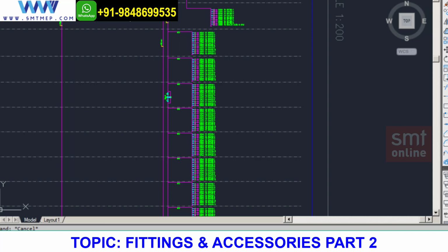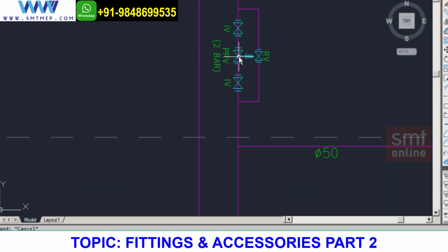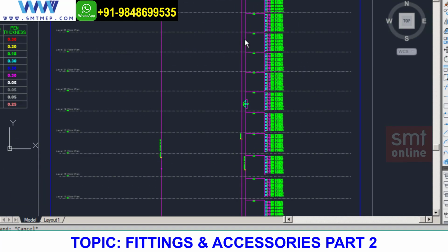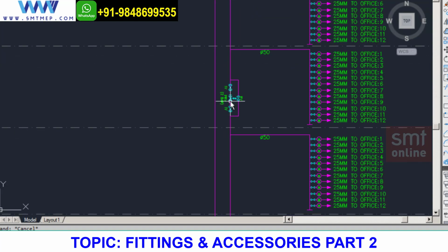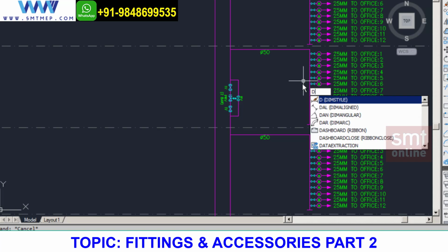Okay, so as you asked, here everything will be zero because it has reduced the speed. It has stopped that velocity, it has consumed it by means of the spring. It tries to compress this. That energy is being converted into compressing the spring. Okay, that became completely zero. And again, the water is going down. Again, according to me, this might be 60 psi or nearby 60 or exactly 60. There is one more PRV over here. Oh, sorry, PRV.